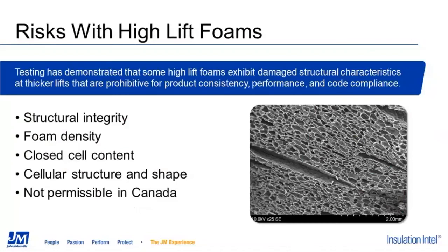Johns Manville has completed extensive testing on high-lift foams and identified discrepancies between the values you might find on a technical data sheet and lab-tested physical properties on high-lift foam sprayed to the manufacturer's recommended maximum pass thickness. In other words, the physical and thermal properties at a typical 2-inch pass are not always the same as those you get at high pass thicknesses, such as 5 to 6 inches, even if the manufacturer recommends such thicknesses.